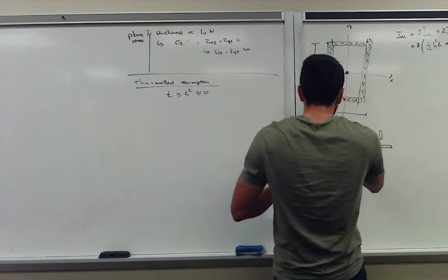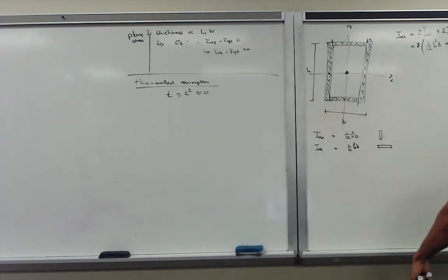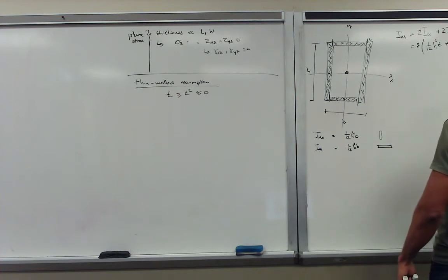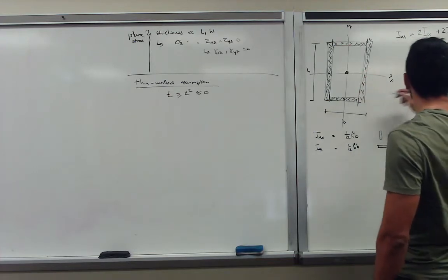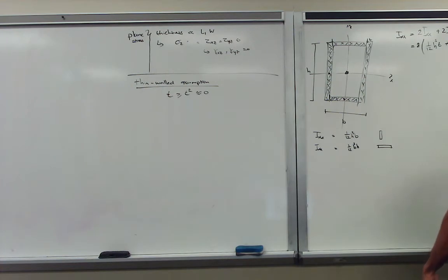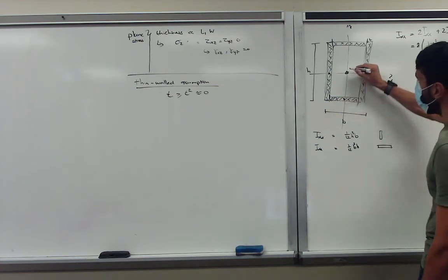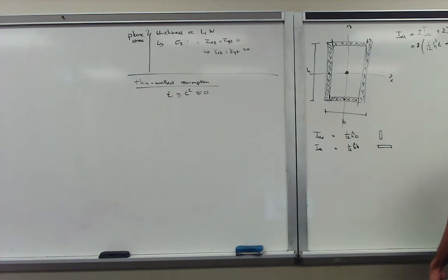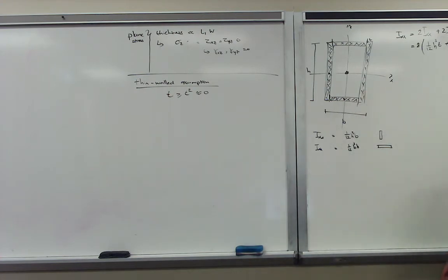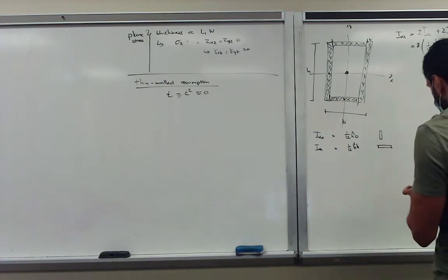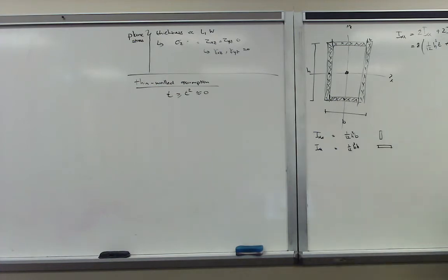So that's t. And then we get basically plus the area, so that's basically b minus 2t multiplied by h multiplied by the distance squared. So technically, if this is h over 2, we get h over 2 minus t over 2, because the centroid is in the middle. So this will be officially our moment of inertia for this cross section.